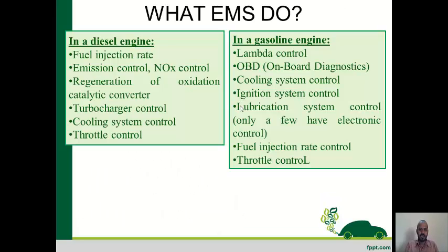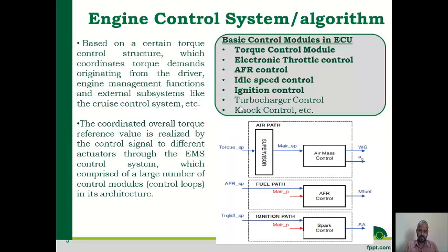What does the EMS do in the case of diesel engines and gasoline engines? In both engines, it will control the fuel injection rate, emission control, NOx control, turbocharger control, and throttle control, and there is no limitation on what it can control. For example, in lower-level electronic control, it will control basic functions like fuel injection, throttle, EGR, and turbocharger. But in higher category vehicles or higher technology levels, nowadays the cooling system, lubrication system, and radiator are also controlled by an EMS.